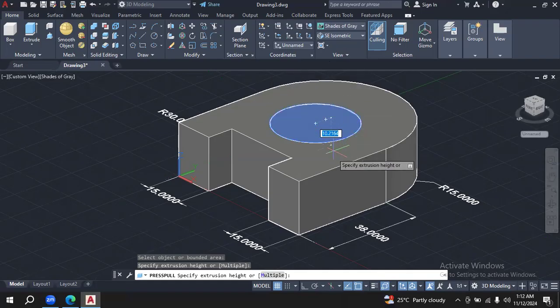And if you take this in negative z-axis, it will create a hole, like if I show you like this, press enter, and then you see here is your hole like this. So from bottom, it is also here. Probably the center point is dislocated somehow.